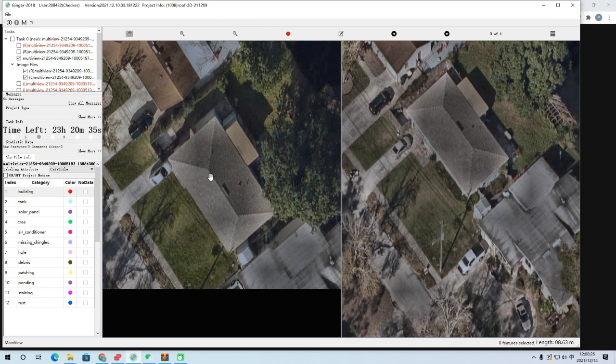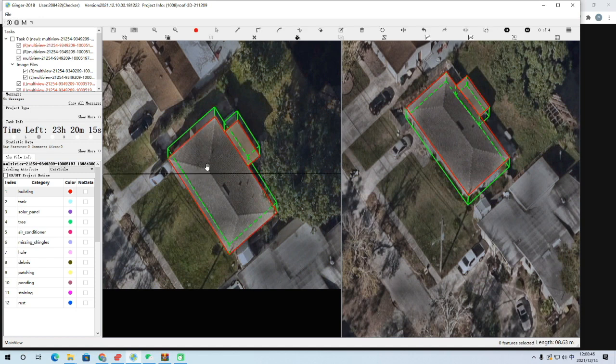Because this roof ridge decides the height and 3D relations with all other roof structures in this building. Imagine if you have the correct length and height information for this roof ridge, then the rest of the thing you need to do is to connect them to the part, and then the roof structure can be done. So remember, this is very important.